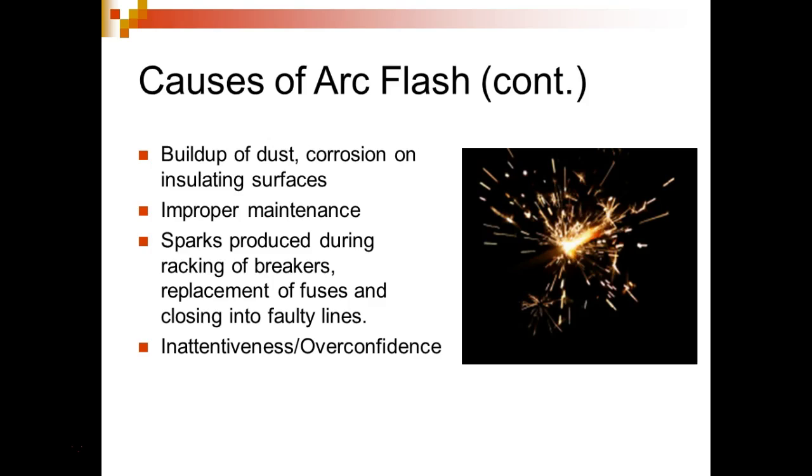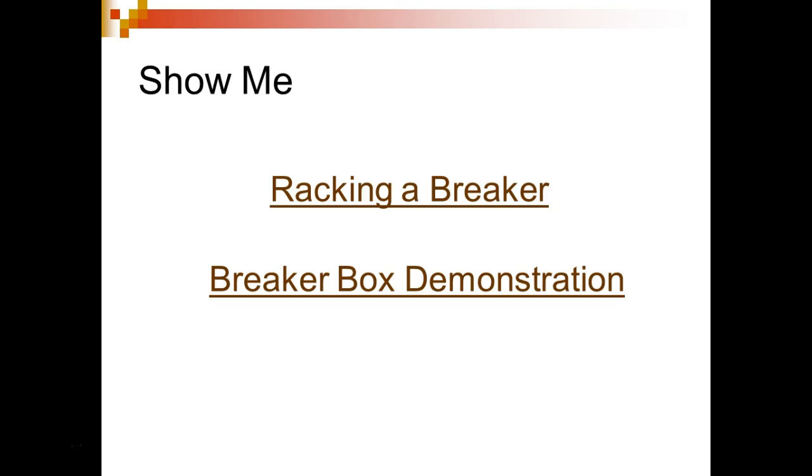I think this is exactly where we're at, right? Racking a breaker, we showed that video already. So what's racking a breaker? Well, technically, racking a breaker is installing a breaker. So even in your house, when you open up your panel box and you push that breaker into those blades back there, that's the same thing, except on these industrial breakers, you're dealing with big ones, right? And like I said, these things are usually inside a box, and they're on rails. You roll them in, and then when they rack them, they actually have some type of screw mechanism where they rack them in.